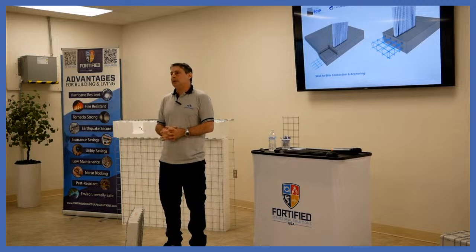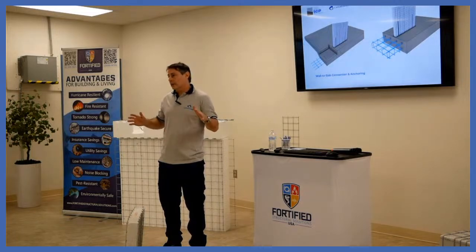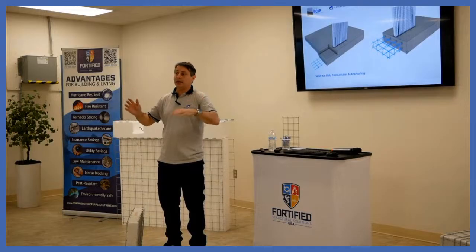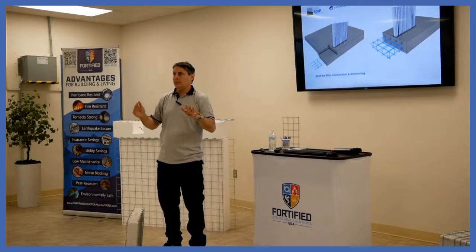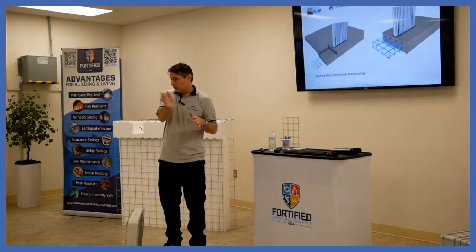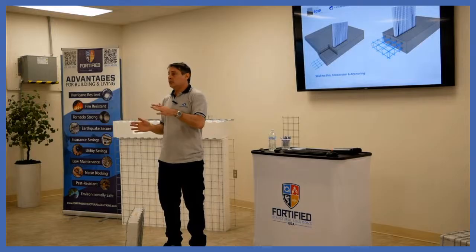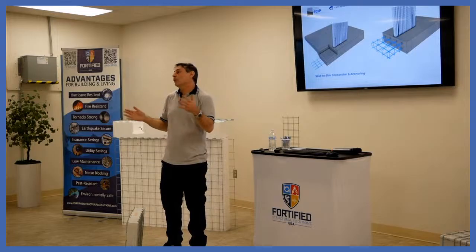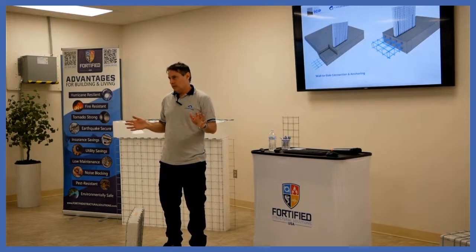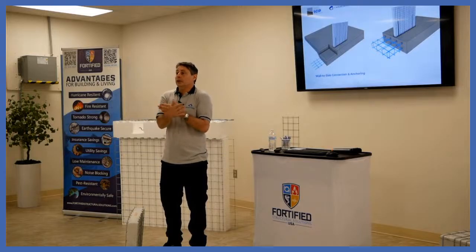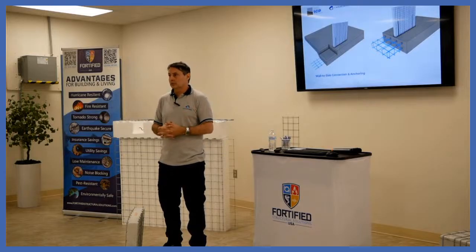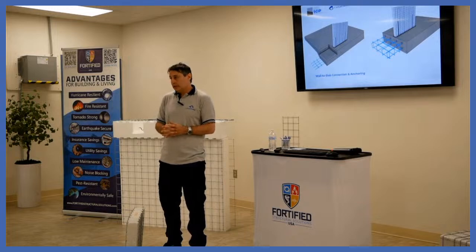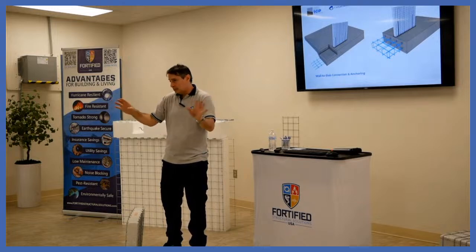Even if you don't want the floor panel to have a header, and if I'm understanding well, you have a sliding door, the place where the slide goes inside the wall can't be a wall made out of panel. That is not possible. It won't work, because we have the connectors in the middle. I'm just talking about the header itself. Yes, we use the header panels as a header.